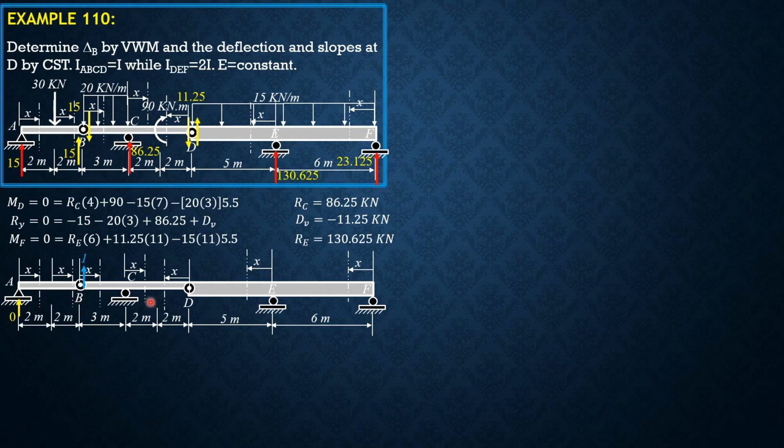So considering BCD, this should be 1.75 downward because the equation is reaction at C downward, summation moment D, times 4 equals 1 times 7. So 1 times 7 over 4 is 1.75 downward. Then summation forces Y, because this is downward, this should be 0.75 upward. Then by action reaction, 0.75 downward.